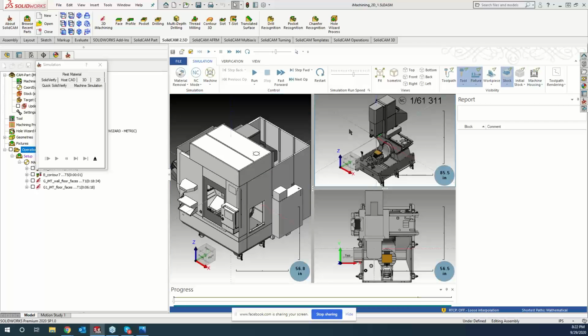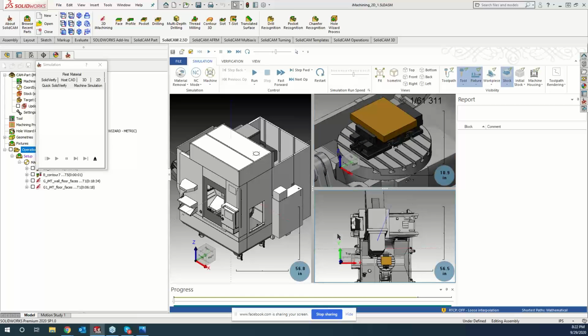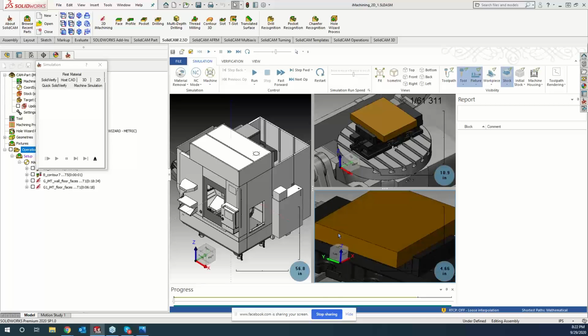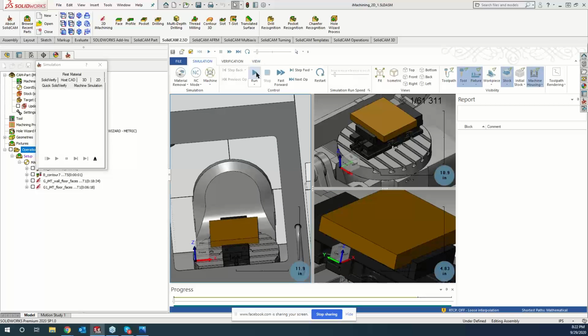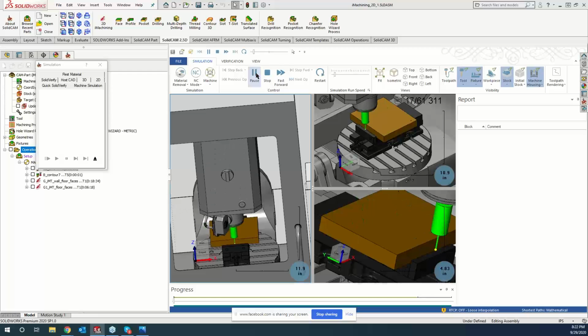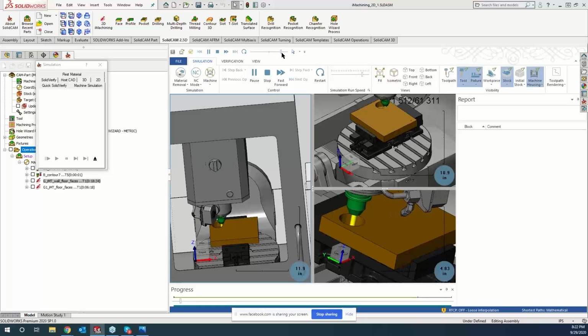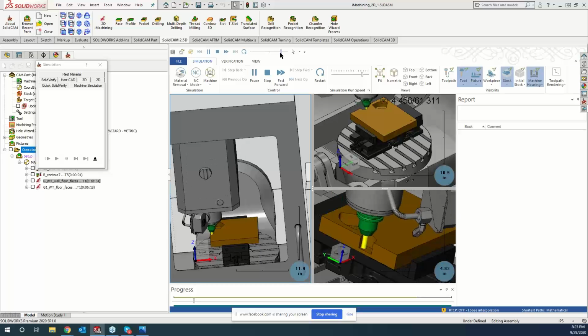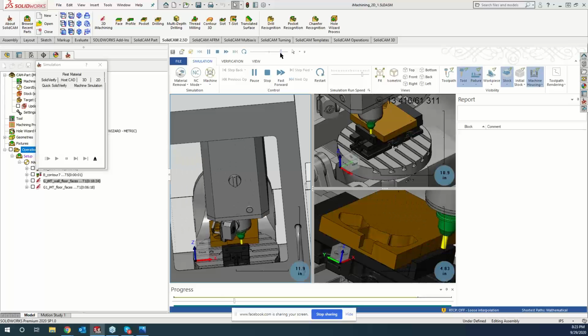Now on my Machine Sim, I have it set up as a 3 view. I got the right side here, I'll go over here and get the left side, and then this one I'm going to get a straight on view, and we'll slow it down. So we're doing our probe Z hit, doing our XY, and now I can speed this up here. And you can see that we're doing our iMachining to get all those pockets in there. Any questions from anyone?